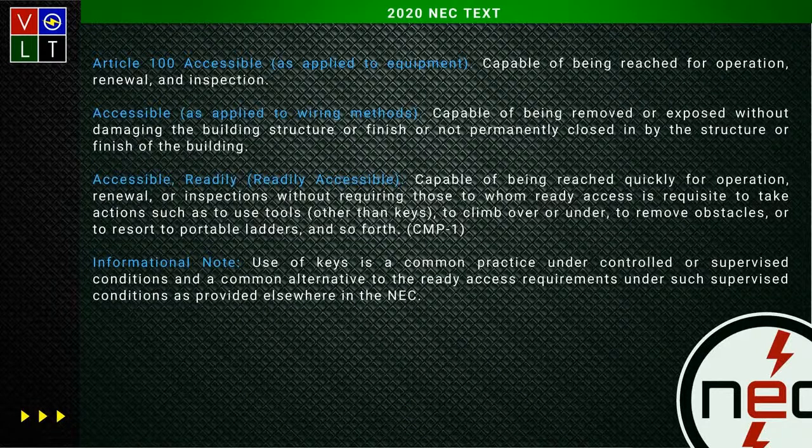There was some talk that it's not required, that you could put it on a regular outlet if the equipment itself comes with integral GFCI protection. I've never seen that. I've installed hundreds of them, and I have never seen a manufacturer provide one. Pretty much all of them that I've installed, we had to install our own cord even. They just had the terminations in there, and we just had to run a cord out and then plug it into a GFCI.